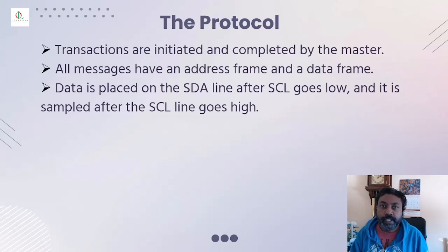Data is always placed on the SDA line, and when the data transfer happens, first the SCL will go low and it will be sampled, and after the line goes high, then the data will start to transfer, which you will see in the next slide.